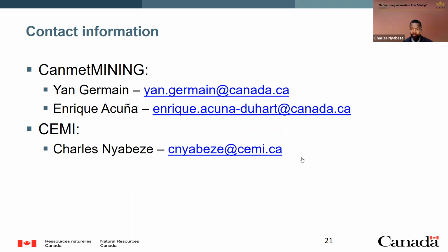So the first question is about the exhaust of the air. Because I have some ventilation background, I know that between the exhaust and the inlet, you can probably look at about 10 degrees difference. And I've seen that through some of the other presentations that you have done with some suppliers that provide that type of technologies as well. So it's kind of in that range.